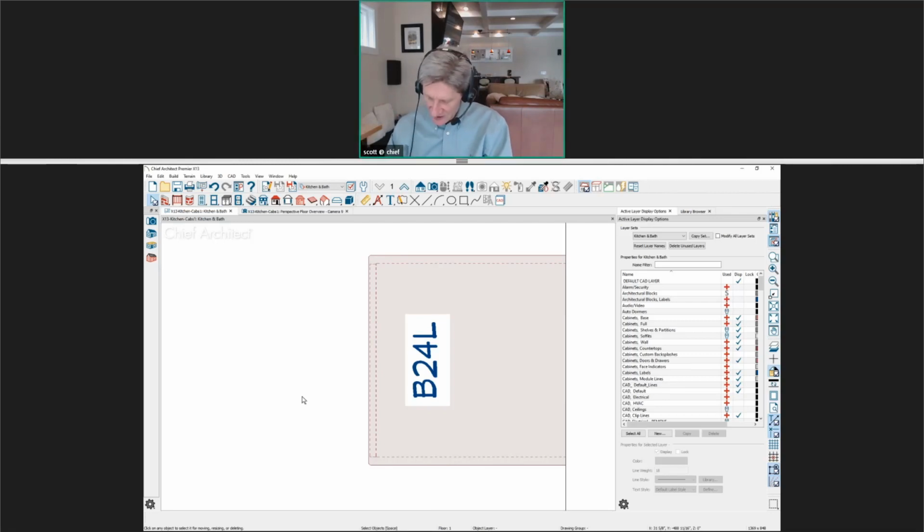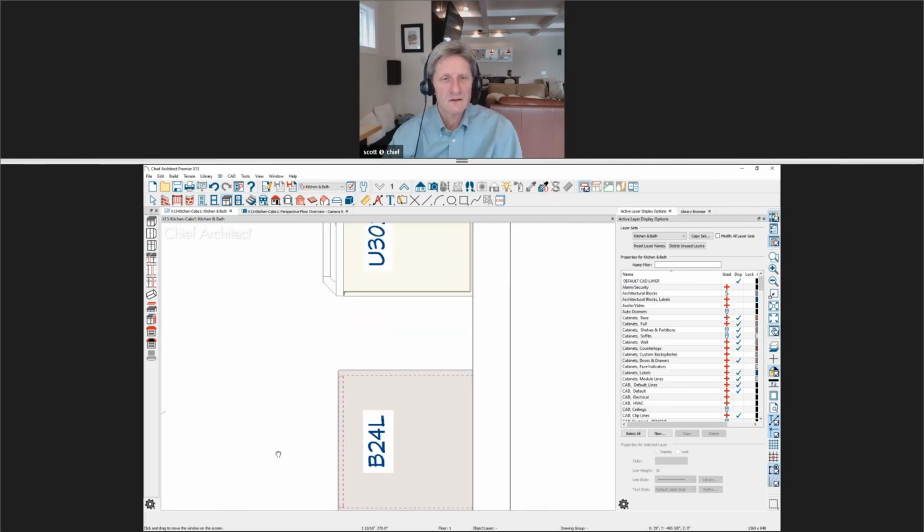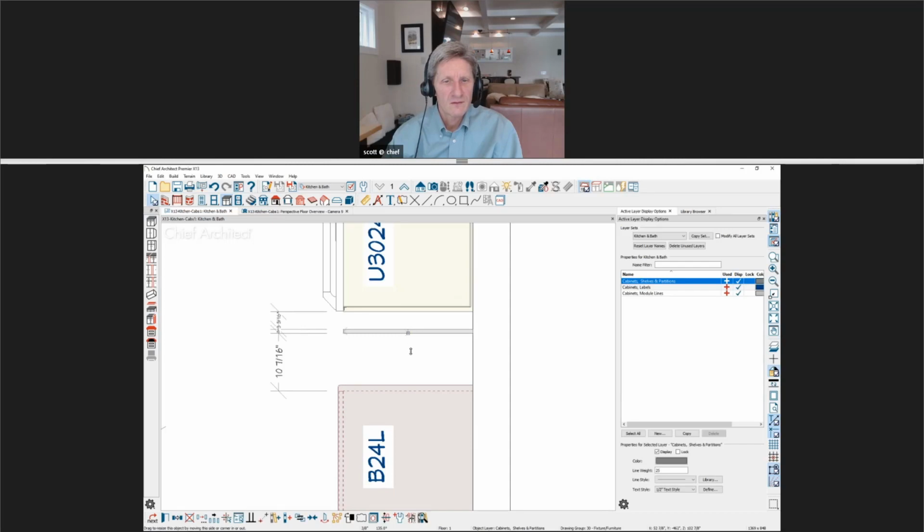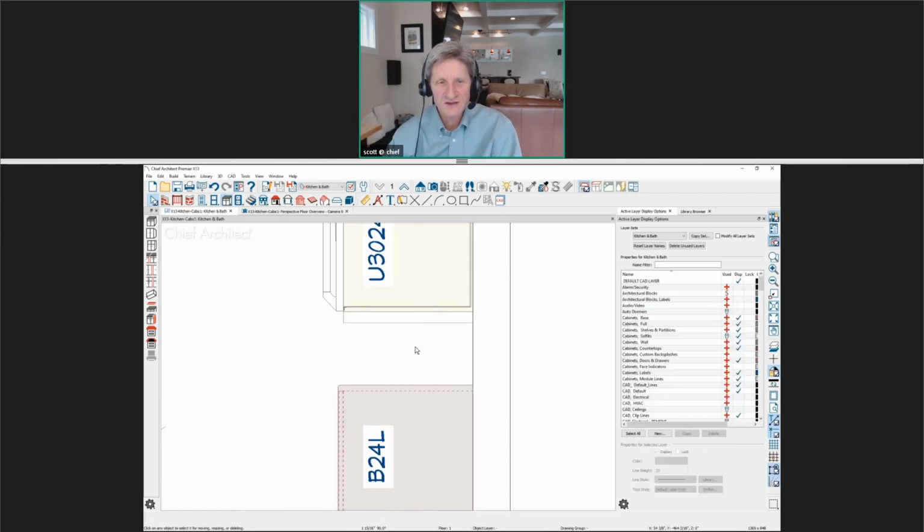Okay, you had one more question. Yes. Partitions. Let's see, if I add a partition, for example, next to, I like to use partition sometimes because I do not have the toe kick. It's easy, it's fast for a dishwasher return panel. And on my computer, it doesn't snap to the sides. It always snaps to the center. All right, so I have a 2-inch partition that's next to the double oven here. Let's take a wall elevation view and take a peek at this guy.